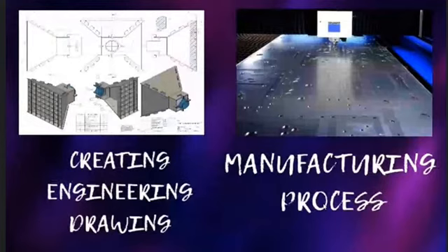Now, create engineering drawings. After designing and completing a 3D model, drawings are created for manufacturing. Flat patterns are included in drawings to show bend lines. A bend table is included in the drawing that indicates the angle and direction of bend. Drawings include all the information that is required for manufacturing, such as surface finishing, coating, plating, etc.